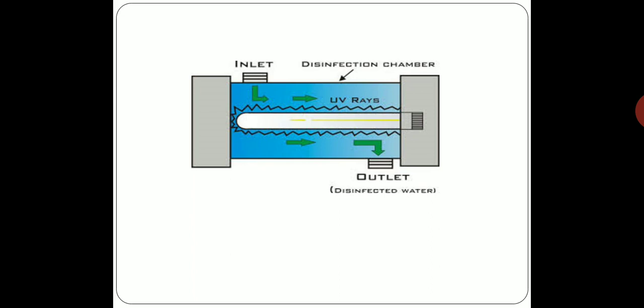The depth of water should not exceed 10 centimeter. It should be colorless and its turbidity should not be more than 15 to 20 ppm. The method is costly and hence not commonly used except for private buildings, office buildings, institutes, and particularly swimming pools, etc.